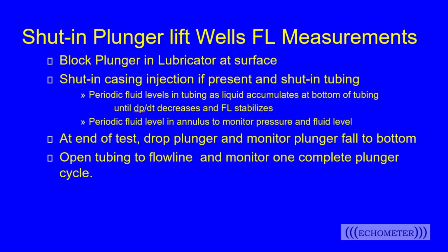Well, what about plunger lift wells? Well, if we do a static on a plunger lift well, I think a good practice is to catch the plunger in the lubricator. Because if we're shut in for an extended period of time, we don't want that plunger to get stuck in the wellbore. So if we're going to shut in for a while, we may want to catch a plunger up there, and then we'll shut in our casing pressure, our casing injection.